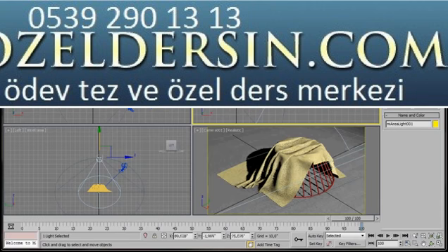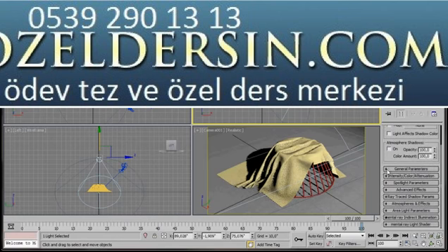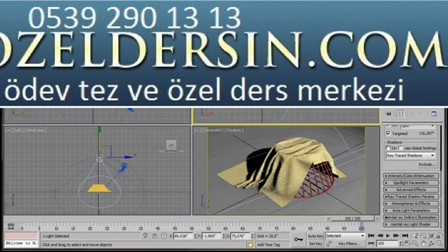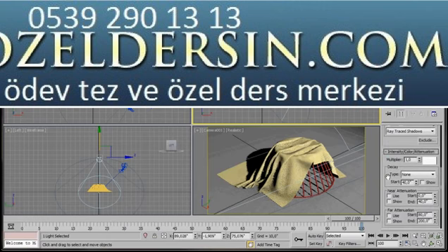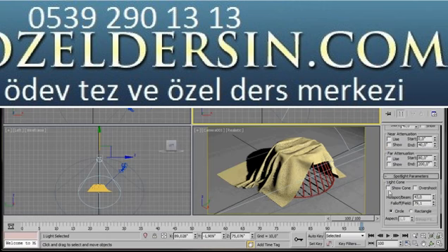Now we can go over to the Modify panel. We're going to scroll down under General Parameters. Make sure we have our shadows turned on and ray traced shadows. We'll scroll down a bit more. Let's have a look at intensity. The multiplier set to 1. And spotlight parameters. Here in the falloff, let's bring it up to 80. Then we'll scroll up and turn on overshoot.